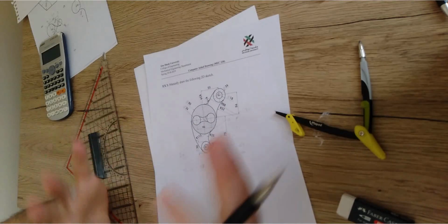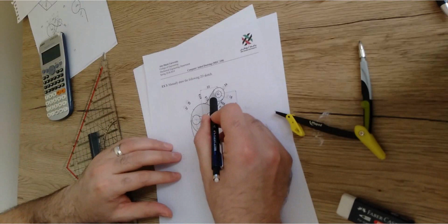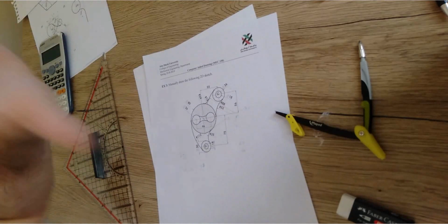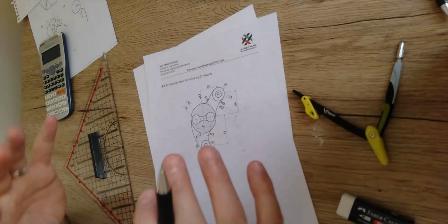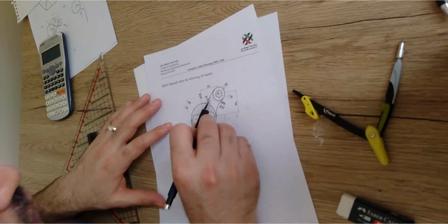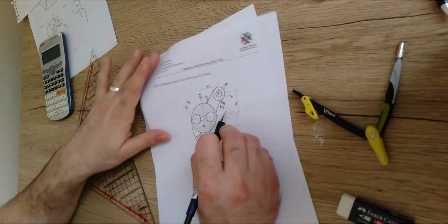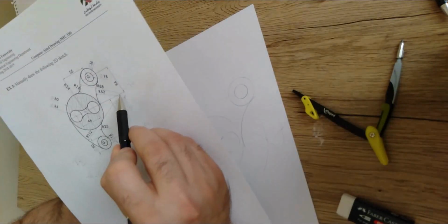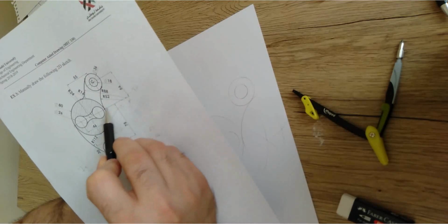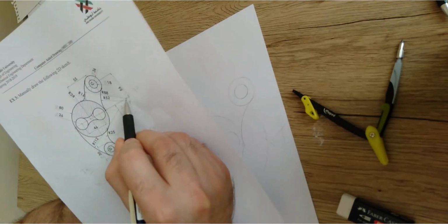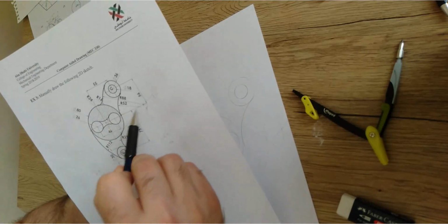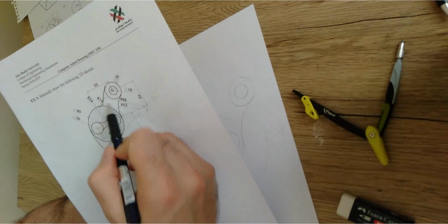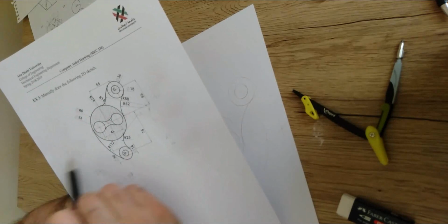So what does this mean? It means that there is missing information here. To draw this curve, you should have the two objects drawn, so you aren't going to be able to draw the two curves. This is because there is one piece of missing information in this case. This information is already given, actually. If you observe the line of this dimension, the 88, you will find that this line is coincident and ends over the center line of this circle. So what does it mean? It means that this point of intersection of the line of the dimension R88 with the center line of the circle should give us the center of this big curve R88. Make sense? And this is what we're going to do.